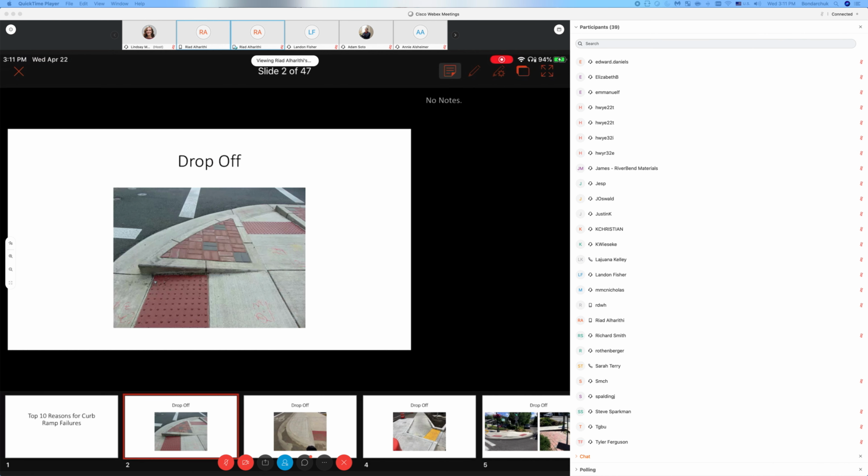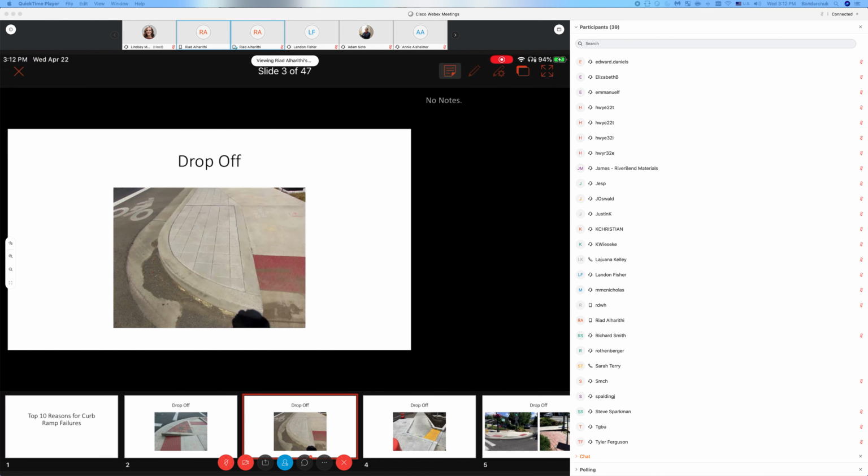The first one, we talked about, is the drop-off, similar to the concept of the standard drawing we talked about. What makes this ramp a failure is basically this concrete surface, the hard surface. In the standard drawing we talked about earlier before the break, if this was a soft surface, then that would be okay. The reason is a person could be wandering here and they could come up to a drop-off here. So that is one of the reasons this type of configuration is failing.